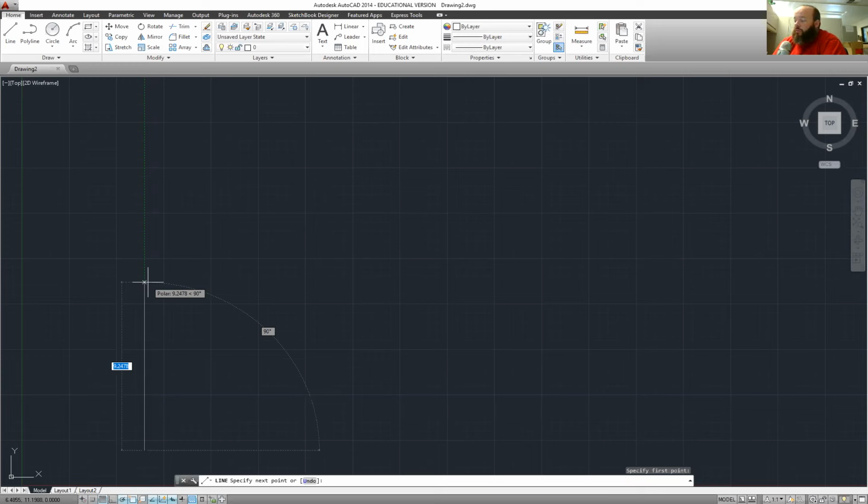So what we're going to do here, we're going to enter our first dimension of 5, hit enter. Okay, we're going to come to the right here. Next dimension of 3.5. I enter it in decimals, 3.5. Enter. Okay, we're going to hit enter one more time because that's all we can do from that point. Now if I hit enter again, it takes me back to the previous function that I used. As I get close, there's the box that appears over that intersection there. That's also one of the snap functions. So now when we click there, it actually starts the line exactly where those two lines meet.